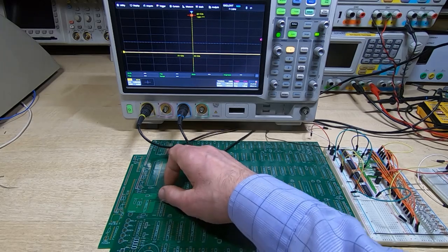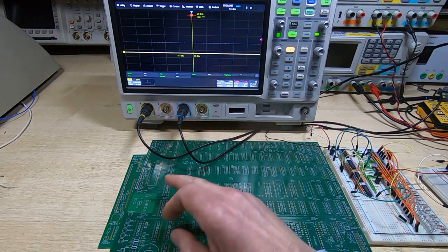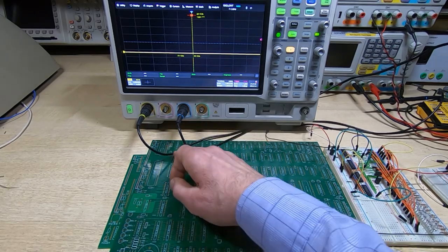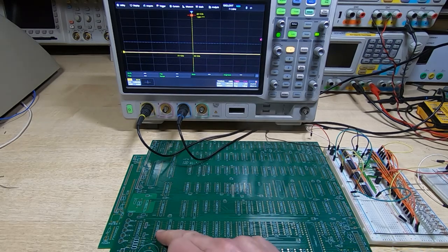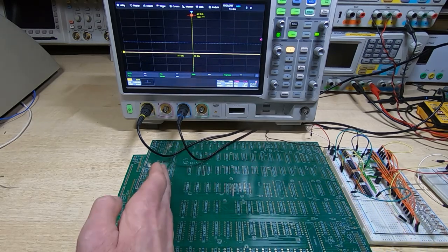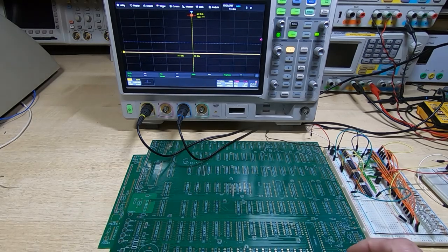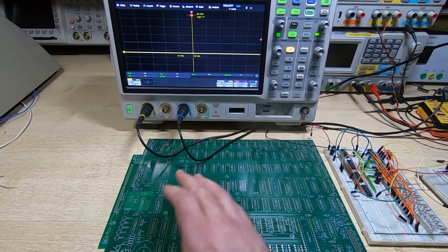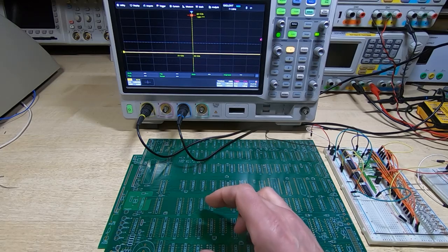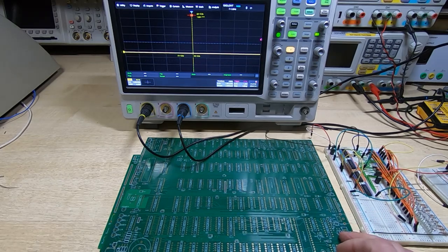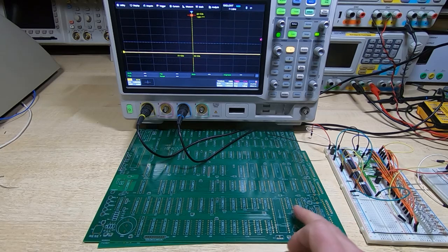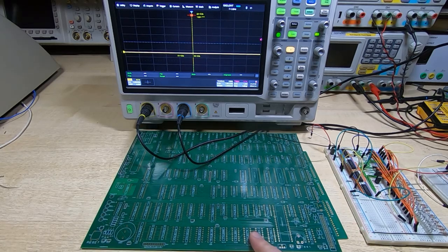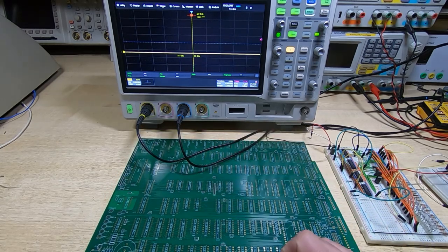We've got the Z80, the ROM, clock and clock divider, and then this column of ICs are buffers that effectively buffer the Z80 from the rest of the system. And then at the bottom here I've added the DMA counter, and on the right bottom corner we've got the floppy drive interface. The rest of the board, the layout's completely changed.